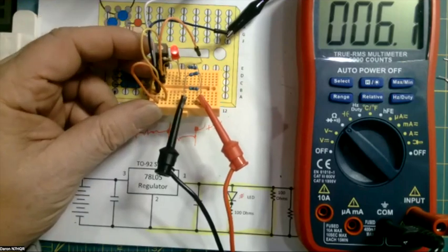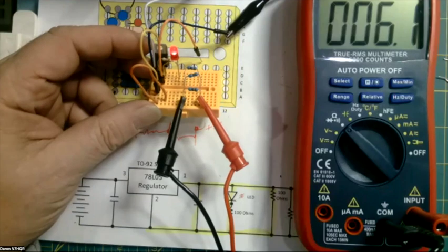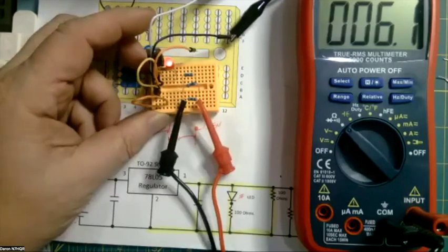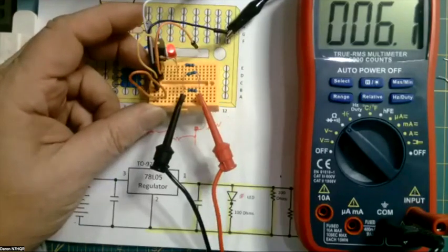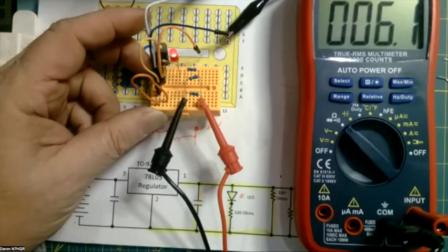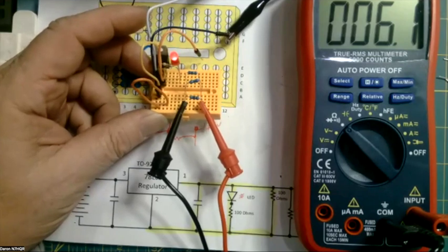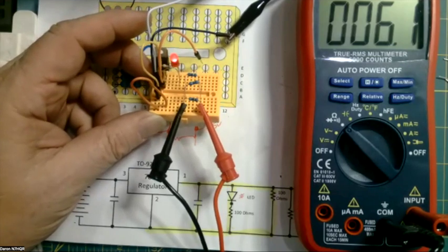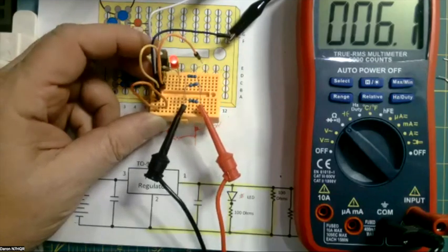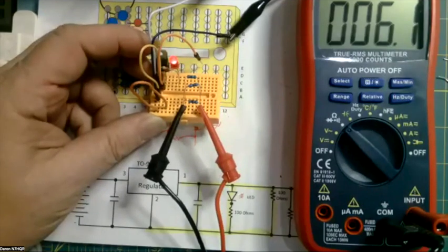Oh, okay. Well, the next thing we'd want to do is find out what the current is. Yeah, the next thing I want to do is find out where there's a beer. Yeah, okay. That's going to be a lot of current. You want to try to hook that up to power with 6 ohms? Um, I don't know. 6 ohms and 5 volts. Yeah, that is a lot of current. It should be about 900 milliamps, but I don't know if our battery would put out that much. Are you using my power supply? Yeah, that's a lot of current.